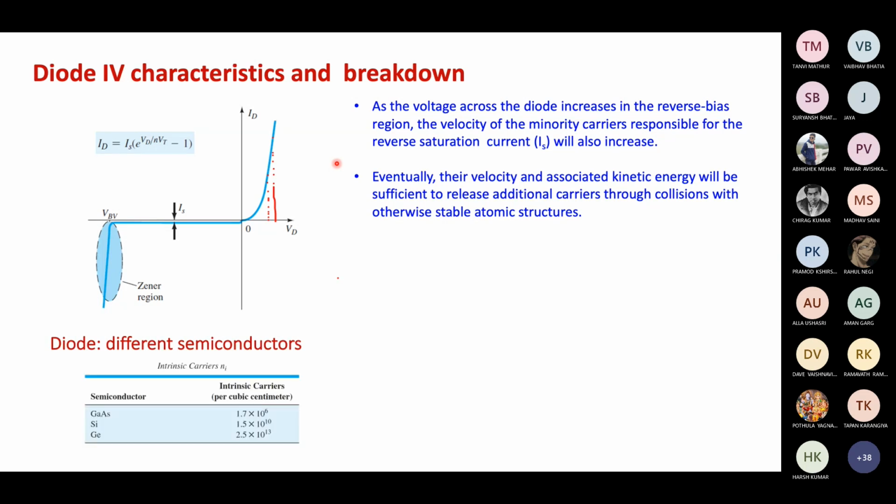So this is mostly about the IV characteristics of the diode, and for a silicon diode, the voltage at which this current in forward bias becomes extremely high is around 0.7 volts. And that is also known as the cut-in voltage of the diode. So that is the voltage after which a very high current starts flowing in the circuit, which means that the diode behaves like a short circuit after this voltage. It behaves just like a wire.